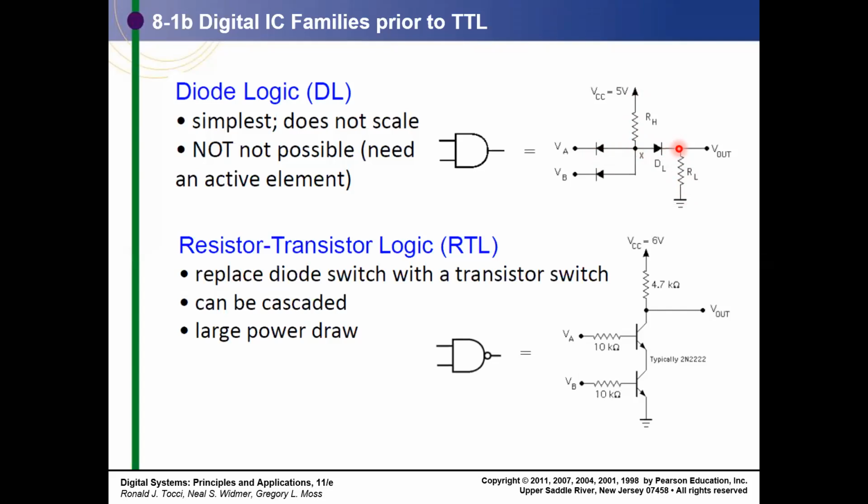High voltage means within that logic range. So this node was rising up to only 5 volt minus one diode drop. So this will go up to 4.3 or something like that, depending on what diode we are using. If diode drop is 0.7, it will reach 4.3.